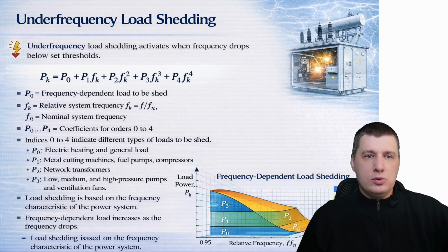When the frequency falls, the protection disconnects part of the load in steps. The goal is to restore frequency to its normal value. This protection must act both for the entire power system and for island areas. For this reason, under-frequency load shedding is installed at many substations. The scheme is distributed and multi-staged. The amount of load disconnected depends on how much the frequency drops.